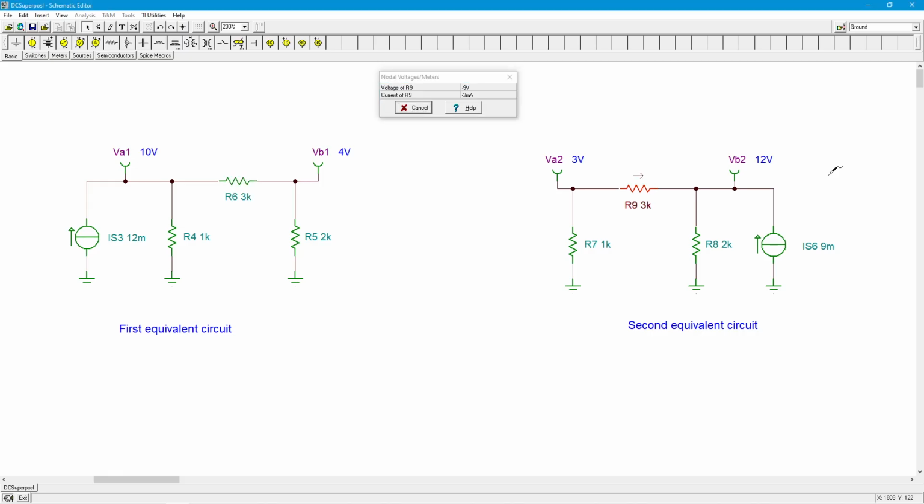Now on this resistor, so we've got 12 volts down to 3. So the reference arrow in TINA is pointing left to right, but you will notice that if you can squint, this actually shows up as -3 milliamps. Well, it's -3 in this direction, left to right, meaning it's positive right to left. All right, so 12 minus 3, that gives us 9 volts. 9 volts over 3K is 3 mils, so there's the 3 mils. So we're saying we've got 3 mils going this way, right? 3 mils going from node B to node A. And then over here, we said we have 2 mils going from node A to node B. So that partially cancels, right?